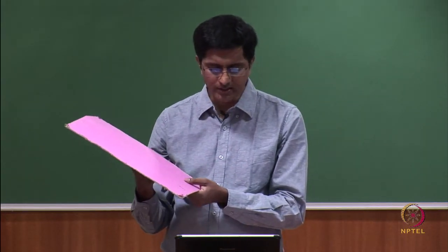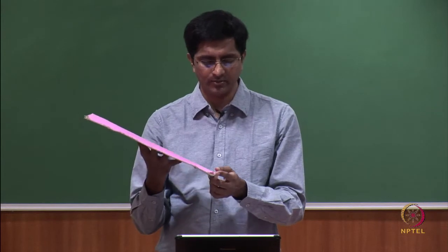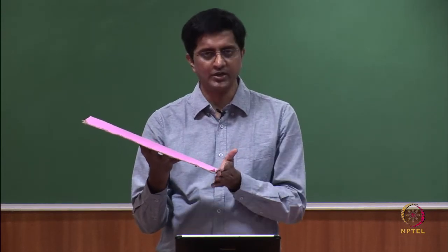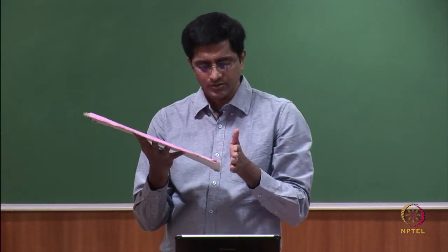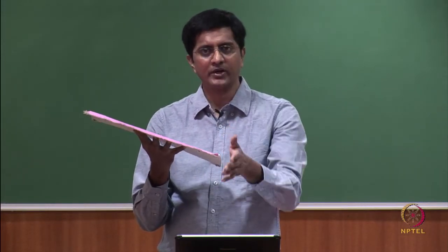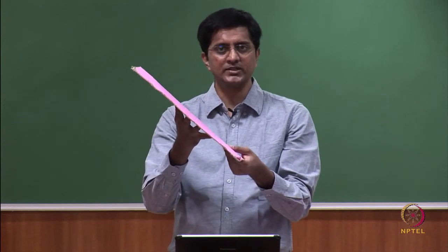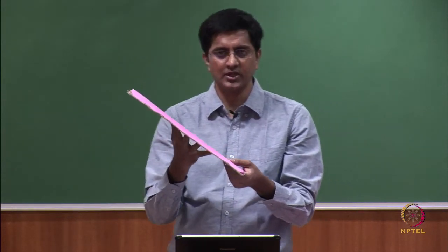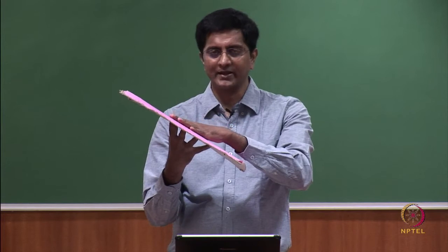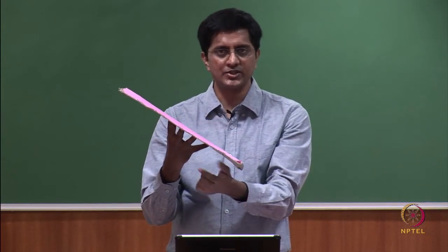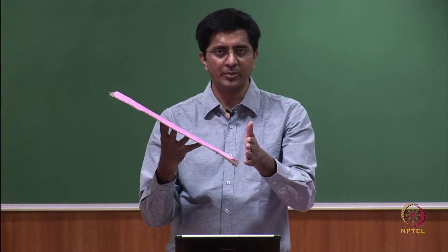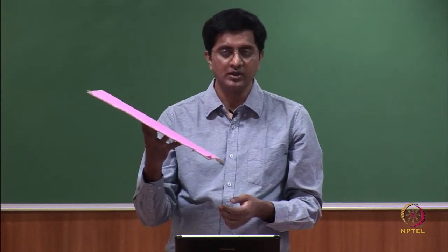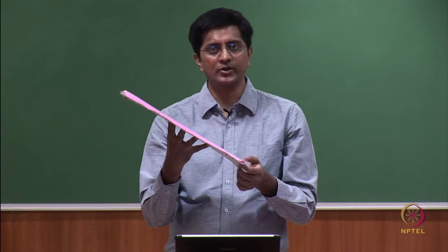It also says that it is perpendicular to the vertical plane. So, let us say now this is the vertical plane. This short edge is perpendicular to the vertical plane. So, this meets the description of the question, saying that we want a rectangular plane which is at an angle of 60 degrees with the horizontal plane and the short edge perpendicular to the vertical plane. So, how do we draw the projections?